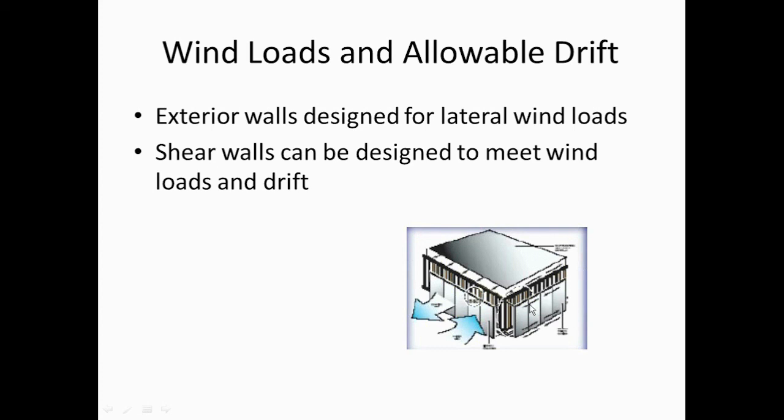must be designed so that in structural engineering you have to design what's called allowable drift. In other words, you have to restrict the building at the highest levels from moving a specific amount. Typically it's L over 500, where L is the height of the building. And that is from a structural standpoint, plus it is also from just a human response to when a building moves. But cold-formed steel framing can be designed as highly flexible to meet these requirements.